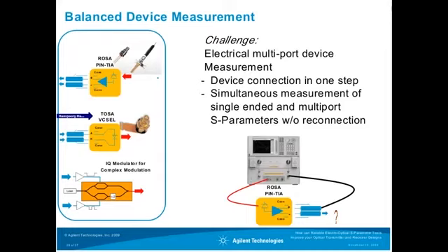Usually we would expect that a laser is always connected on one side to ground, to case. But for those components, in reality, it is not. In contrast, both the anode and the cathode are connected to the hot interfaces of the electrical inputs.